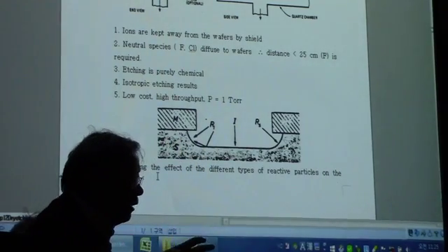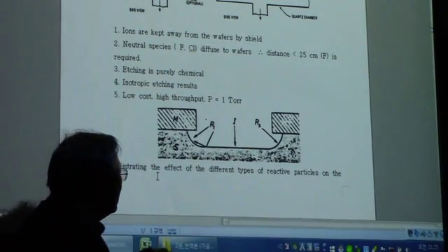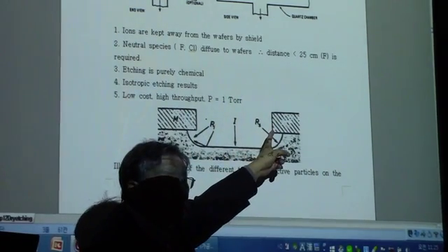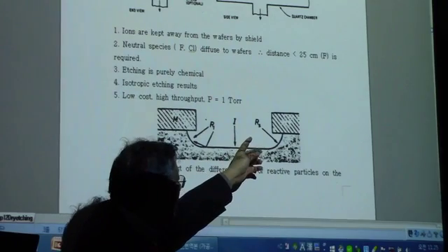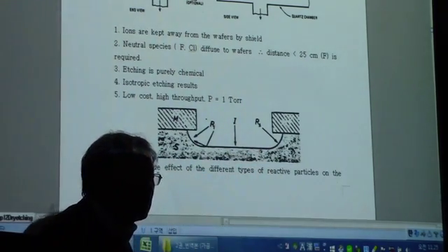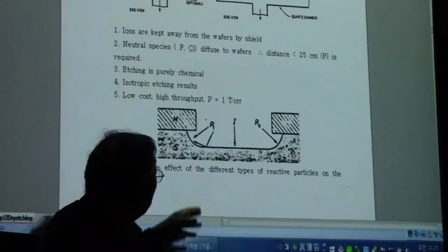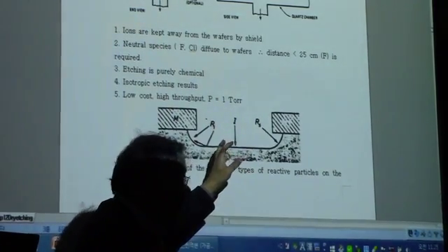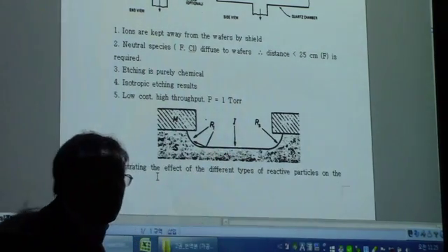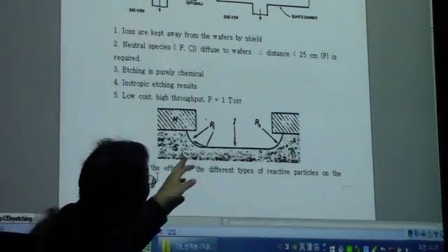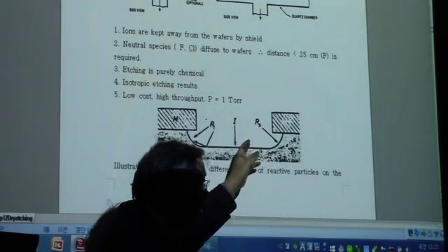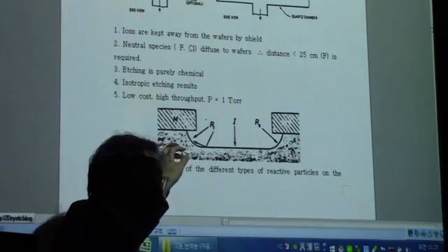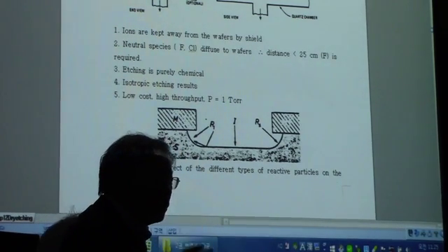And this is a general feature. You're going to have a reactant or etchant: long-lived etchant, short-lived etchant. Short-lived etchant means it has a short lifetime, okay? And then there is a direct etchant, nothing to do with the lifetime. So we can see the 3 types of etchant, and the long-lived etchant is going to contribute to the undercutting mostly.